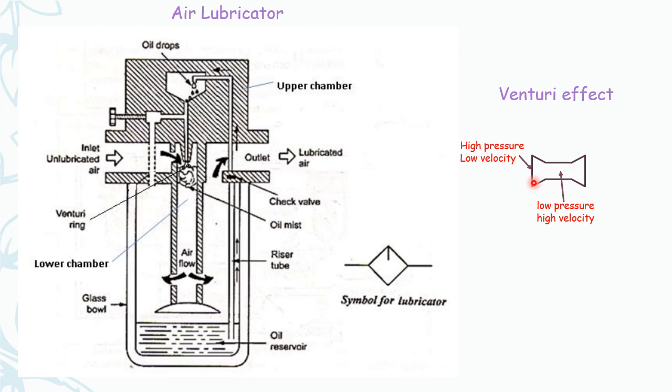So the pressure here at the Venturi will be lower than the oil pressure. Because of the pressure difference, the oil will rise from the reservoir and will be added to the clean air in the form of mist. So this is nothing but your Venturi effect.